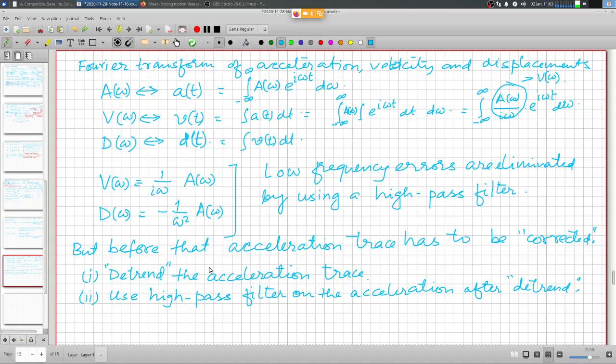There is another issue that will happen after further processing, which is not visible in the acceleration trace, but will be there because of quantization error: the velocity may not be captured as a zero value. Because we are sensing acceleration, a constant initial velocity will appear as zero acceleration in the acceleration trace.